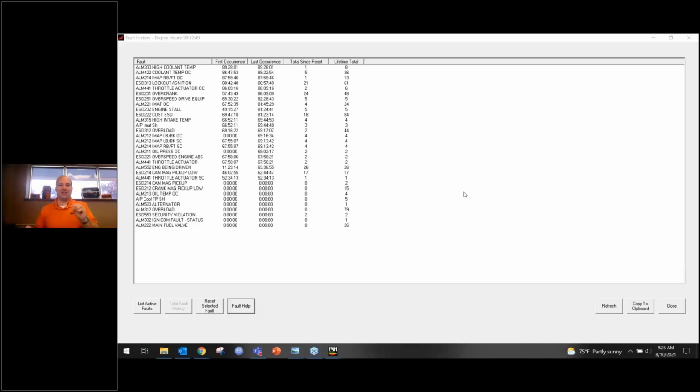Now, this is where we get into the second scenario where it says engine's still running, but it's on limited power, because as it goes to limited power, it starts delaying our timing slowly to try and take it out of that detonation situation. Well, progressively, as we start reading more and more of those detonation sensors, we start saying, hey, detonating, and we get to a point where the temperature is just so hot that it's uncontrollable, and you'll reach an uncontrollable detonation limit, and the engine will shut down.